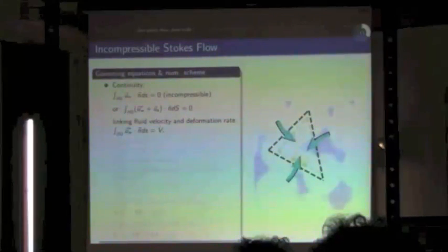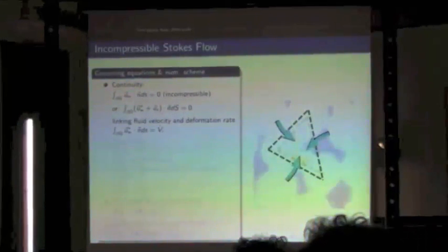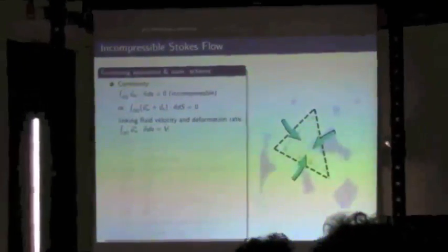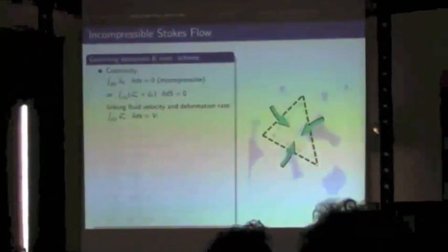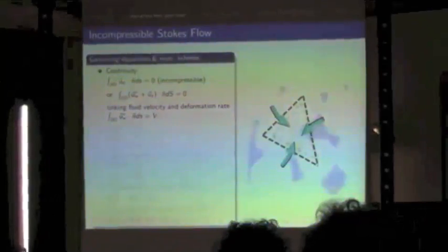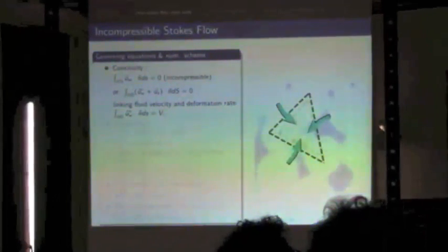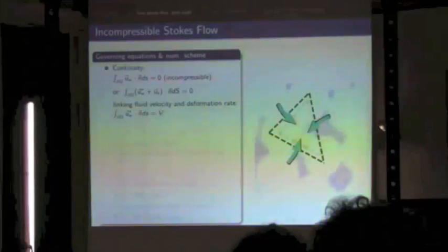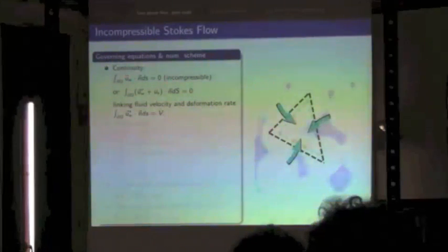First, at the micro-continuum scale, you have a continuity equation. I assume incompressible phases. So mass conservation becomes a volume conservation equation. I write it in an element. It says that the sum of fluxes through the boundaries is zero. But I can replace the fluid velocity by the relative velocity of the fluid, U star, relative to the solid phase.